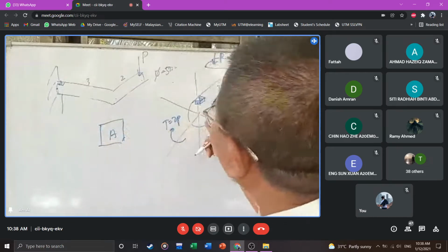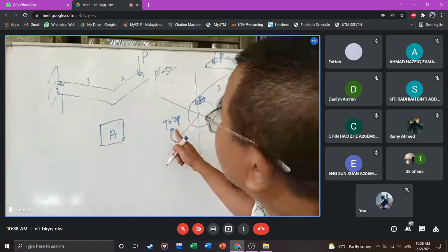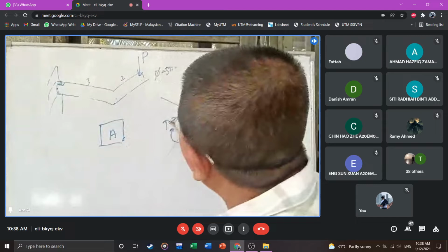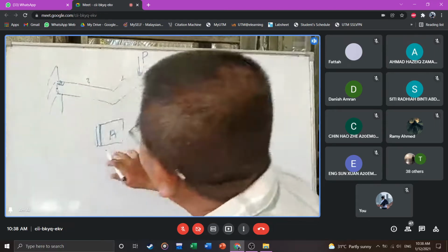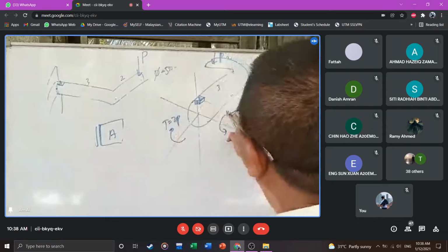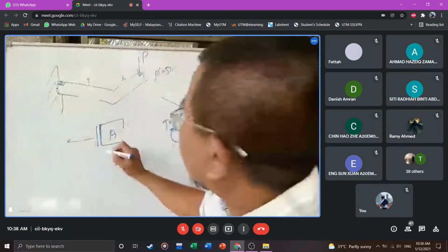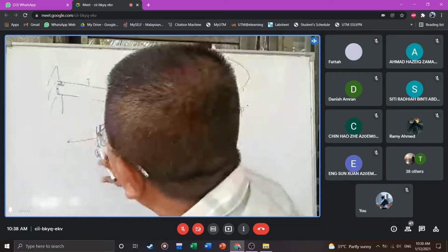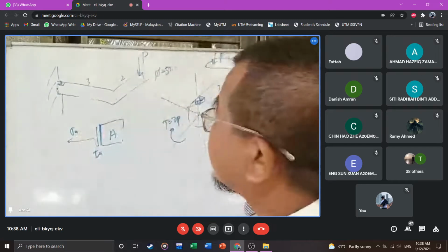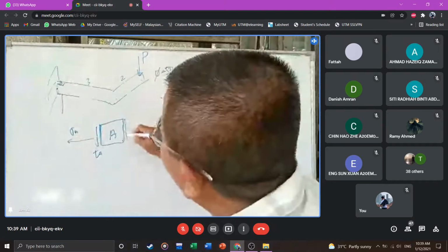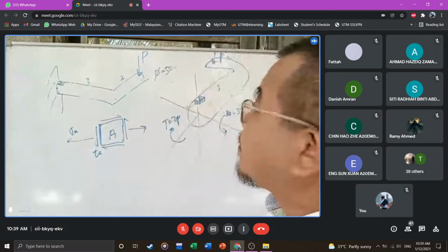So this is how you draw your A there. And then 2P, remember this is 50 mm diameter. So this torsion here will create this surface there, will create a tau there. And this moment here will create a tensile there. So tau A and sigma A. Same thing there, going up. Yeah, we got that one.